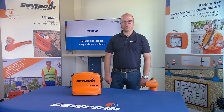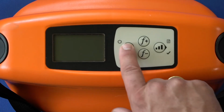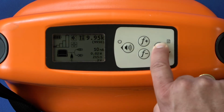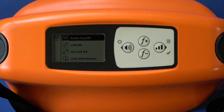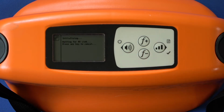I would now like to show you how to connect a generator to a receiver in preparation for the practical parts. Switch on the UT9012 generator. Navigate to the submenu Communications. Select the Link RX menu item. The generator is now waiting for a receiver to connect to it.